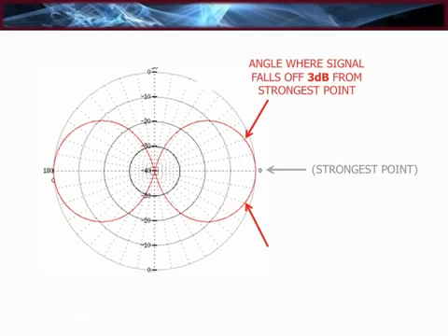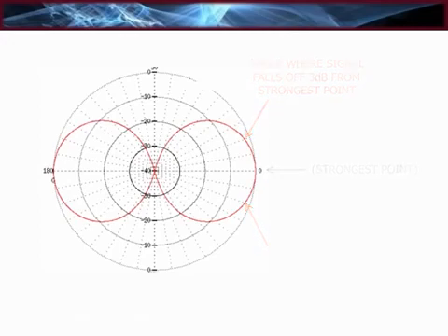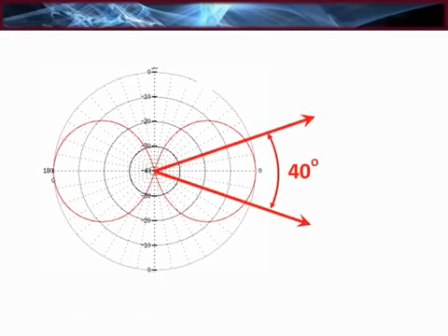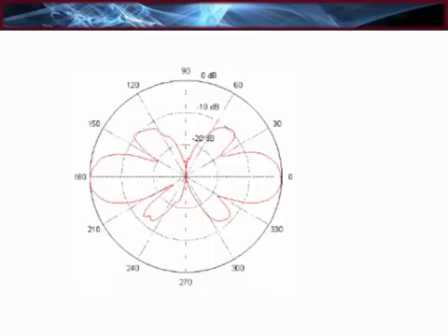On this graph, the concentric rings represent 10 dB each. We can estimate that the negative 3 dB mark is about 20 degrees above and below the horizontal, and that the vertical signal spread for this antenna is 40 degrees. When considering the pattern of a dual element antenna, we can see that the primary lobe becomes more elongated, therefore giving it a smaller vertical signal spread.